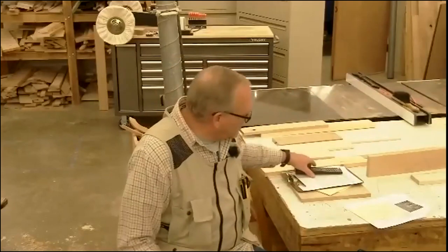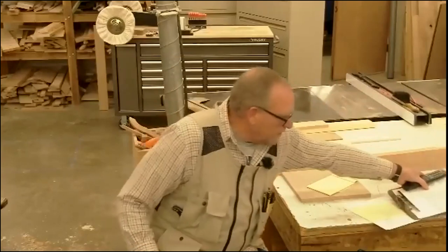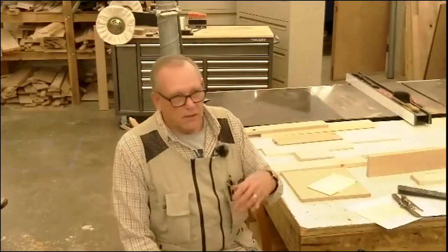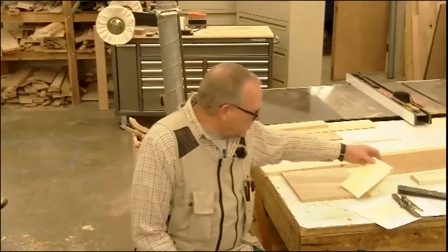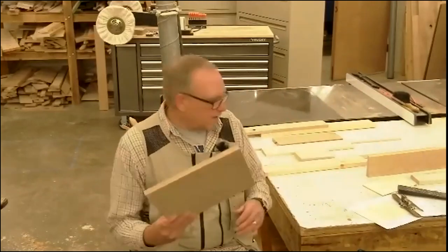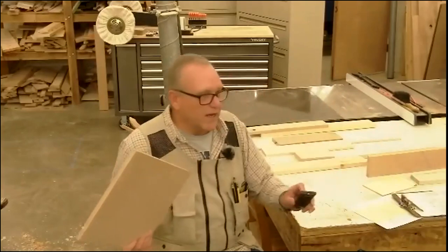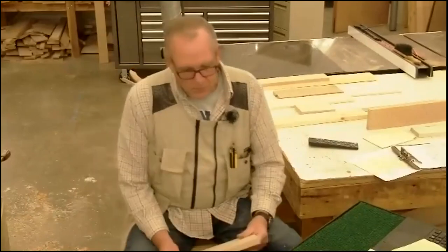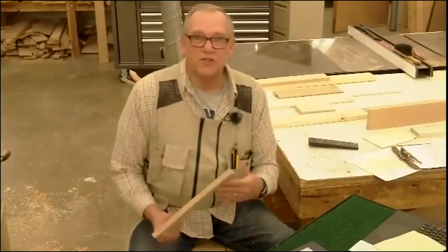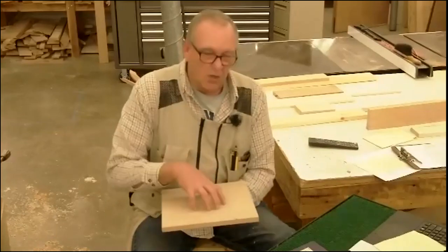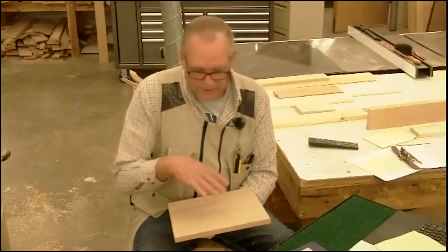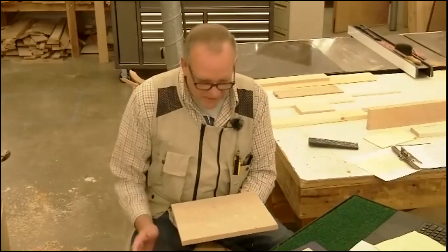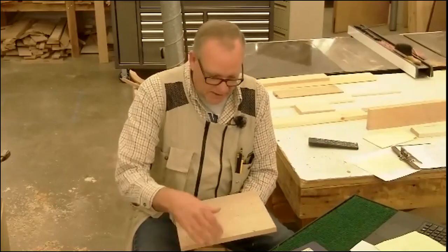So another thing about the joiner is we only joint solid stock, hardwoods or softwoods. We do not joint sheet goods, things like this, okay? There's a reason for that, and it's a pretty good reason, whether you believe me or not. There's a couple things you can safely assume about a piece of sheet goods, whether it's particle board or plywood or melamine or MDF or whatever it is. You can safely assume that the edges and the ends of these boards are already flat, straight, and square, okay?